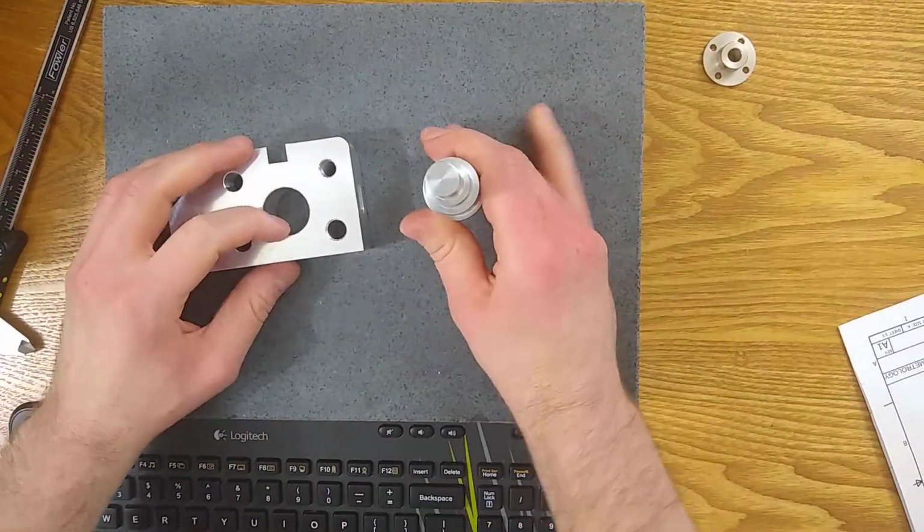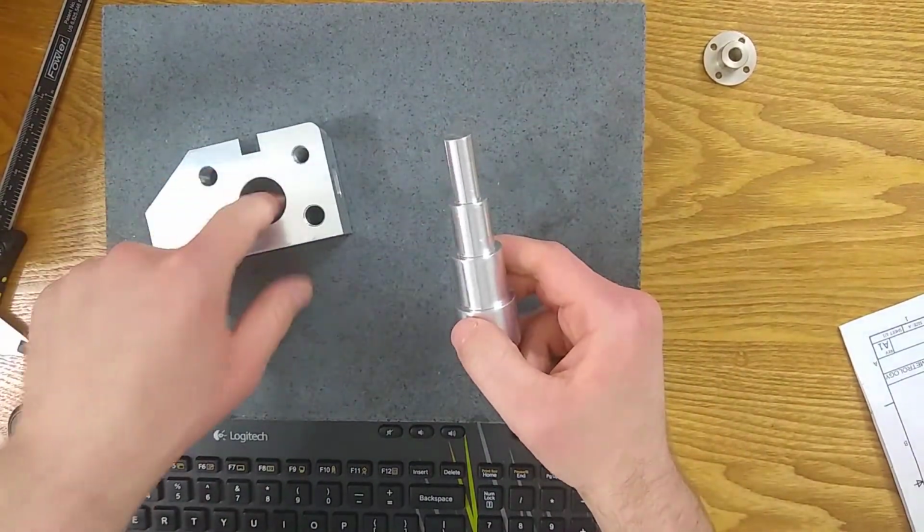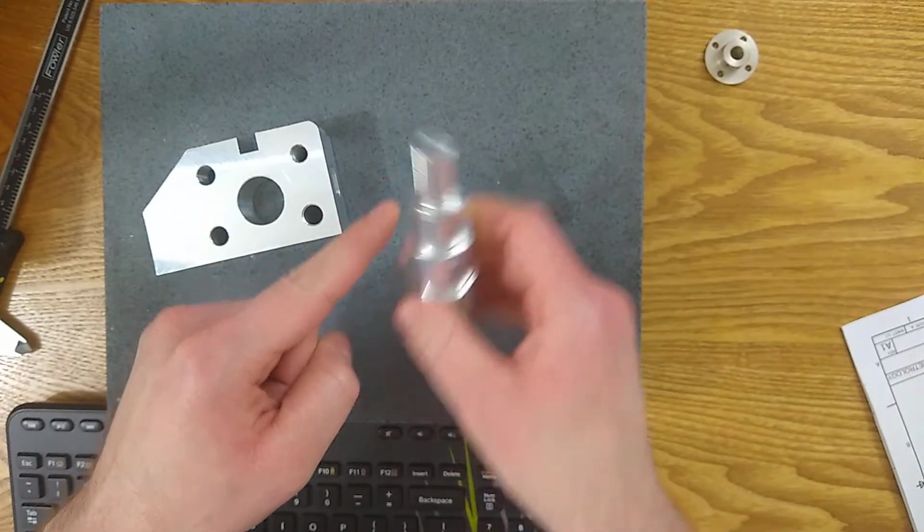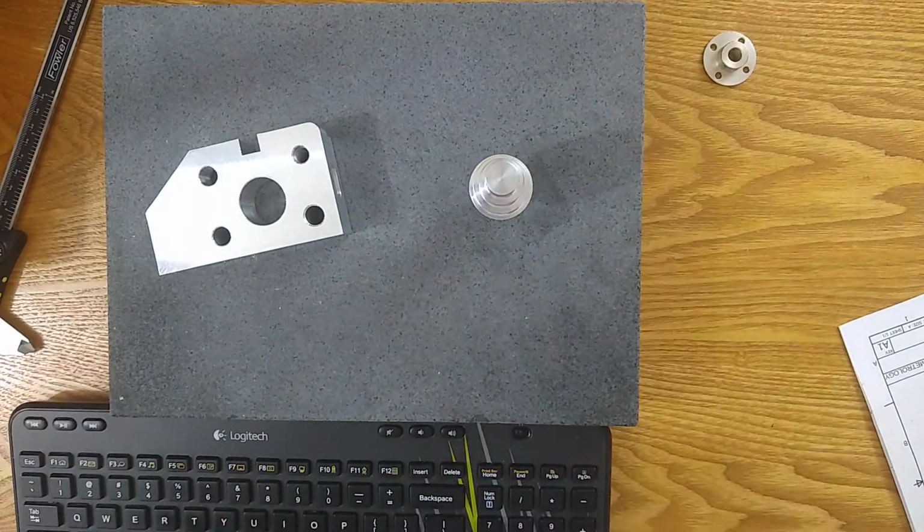So for a hole, either an internal diameter or an external diameter, you can say, how round does it have to be? How round is round? Can it have a little egg shape, little elliptical imperfections? In most manufacturing, the faster you make the part, the more of this kind of error you get.